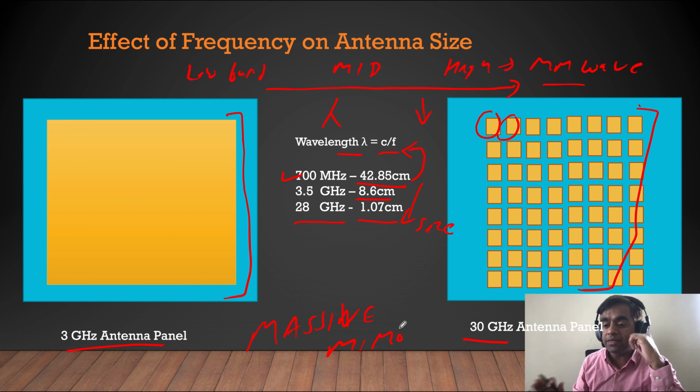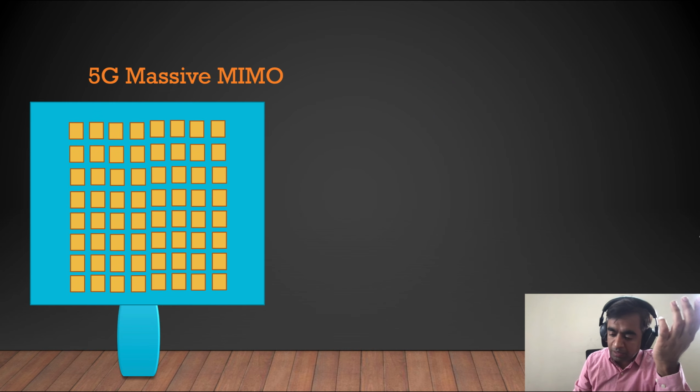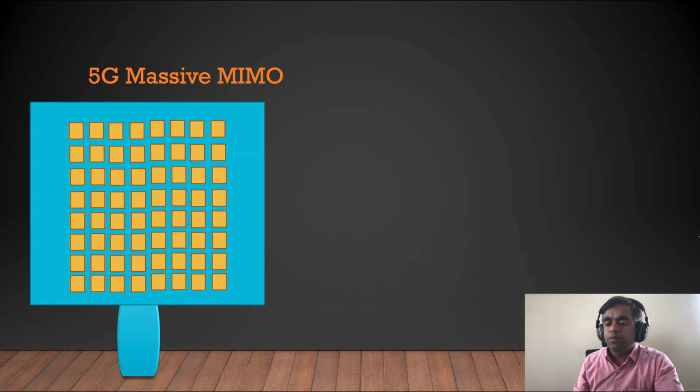Massive MIMO is simply an extension of MIMO, which extends these legacy systems by adding a much higher number of antennas to the base station. You can see 16 units of antenna, 32 units of antenna, or maybe even higher than that. Normally, we say if it is 16 or more, that can be called massive MIMO. But now going back to my previous slide where we were using spatial multiplexing, if we combine all these antennas for the TX, how much throughput can we gain?